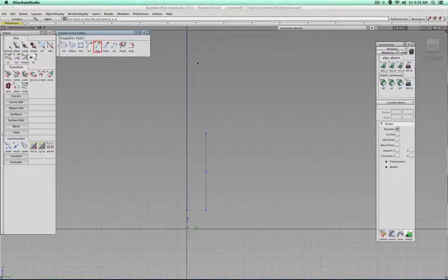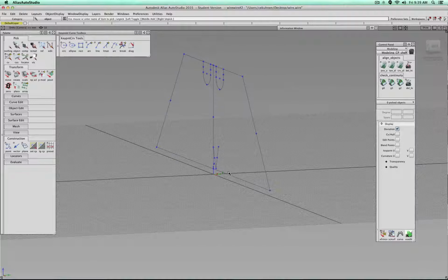Now, for where I'm going to start to draw is actually really important. I'm going to draw Alt click and Alt click, Alt click and Alt click, a line this way. Let's delete this one and let's take a look. Why? The main reason is later we take those vertical lines, extrude them into a surface, and then, for example, cut our metal master to get this cut shape.